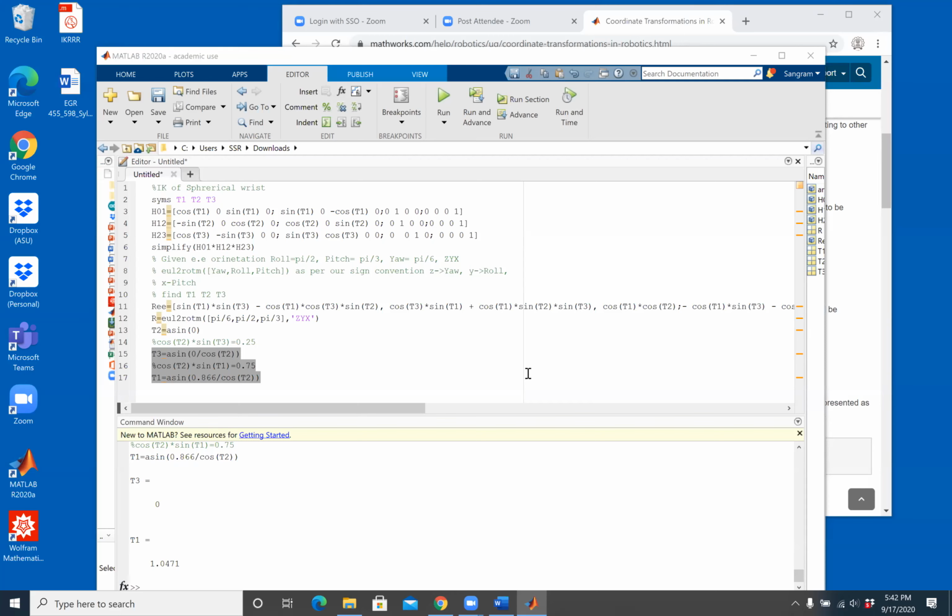And if you look at the last problem, problem 5, it has the first 3 revolute joints. R is perpendicular to R, parallel to R. And what you need to do is solve these two separately to come up with the position solution. So you will find theta 1, theta 2, and theta 3 in such a way that you will achieve the position Px, Py, Pz, and then you will find out theta 4, theta 5, and theta 6.